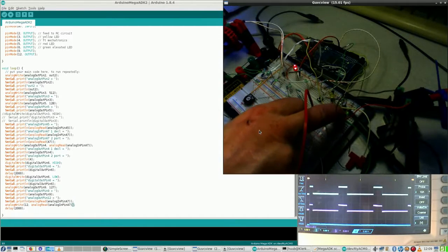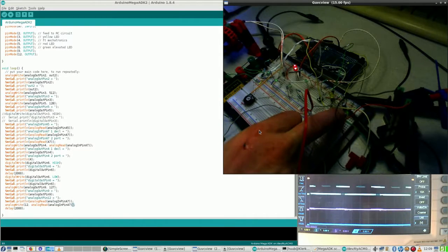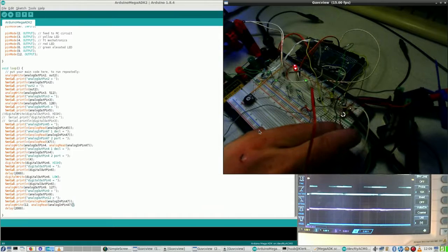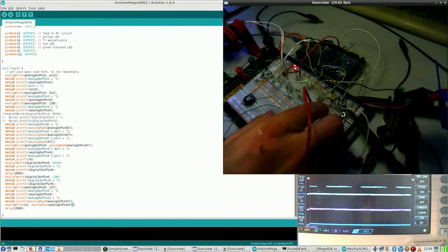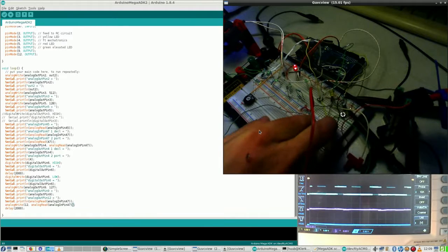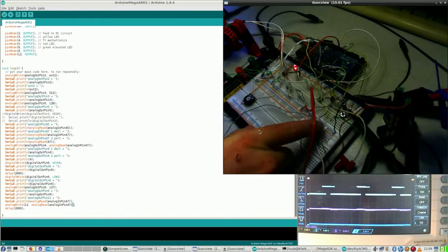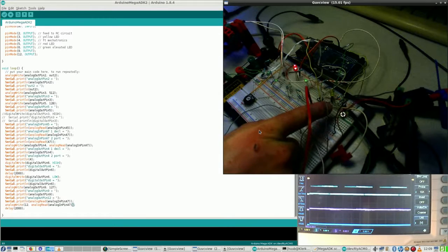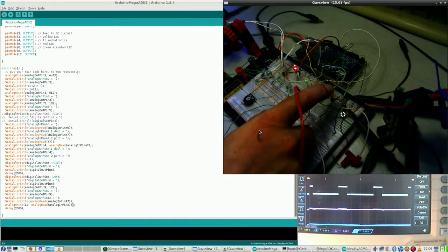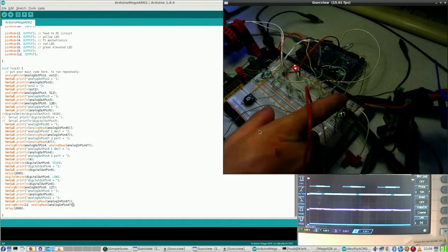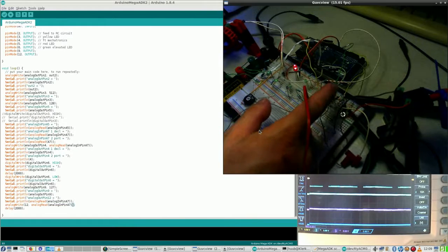I press this button and that is only the RC circuit. As you can see, the LED, which should do anything because it gets its power, gray cable, white cable to the LED, LED to ground, should work, doesn't.